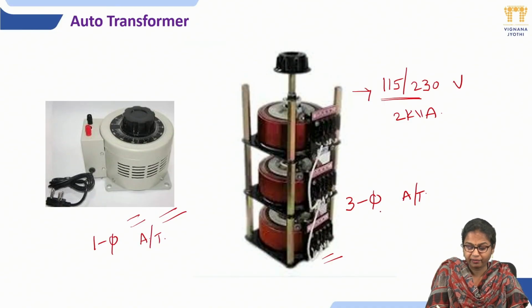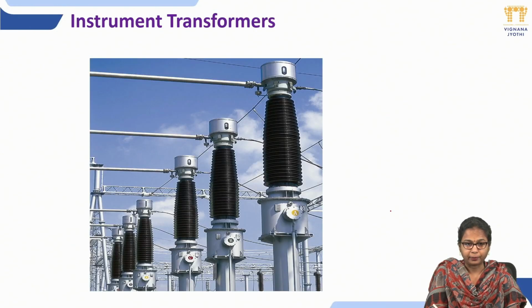We use it to maintain a constant supply voltage, because the induction motor is initially running with rotor speed around 1498. When we gradually apply the brake, voltage dip should not occur. So in order to regulate the voltage, a three-phase auto transformer is used in the brake test of a three-phase induction motor.